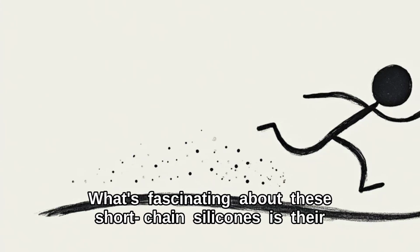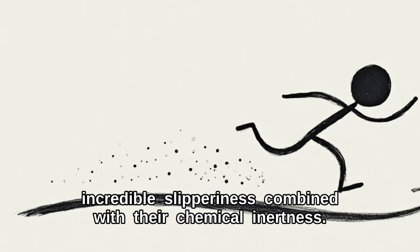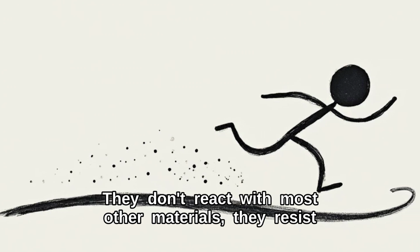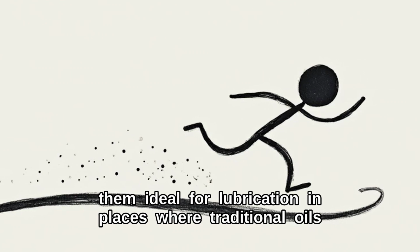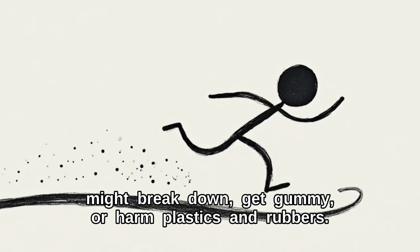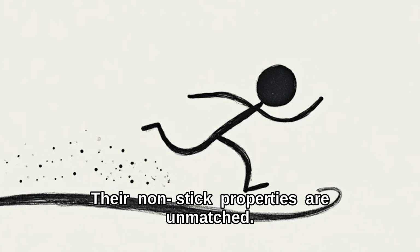What is fascinating about these short-chain silicones is their incredible slipperiness combined with their chemical inertness. They do not react with most other materials, they resist water, and they have excellent thermal stability. This makes them ideal for lubrication in places where traditional oils might break down, get gummy, or harm plastics and rubbers. Their non-stick properties are unmatched.